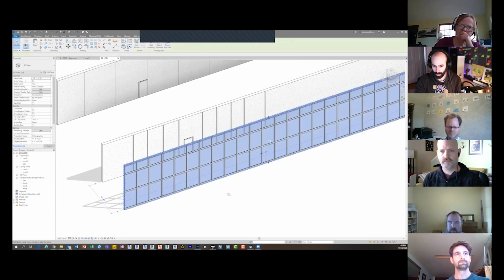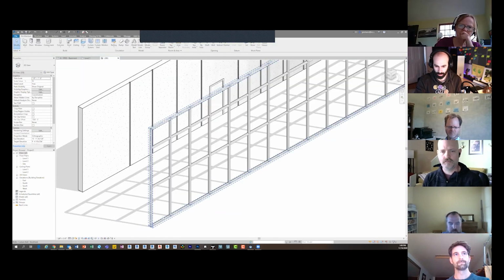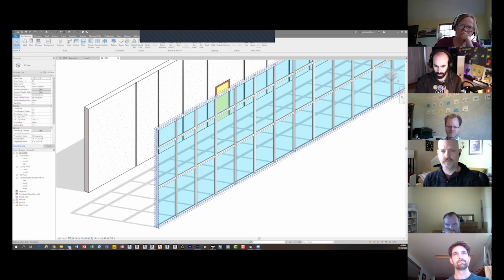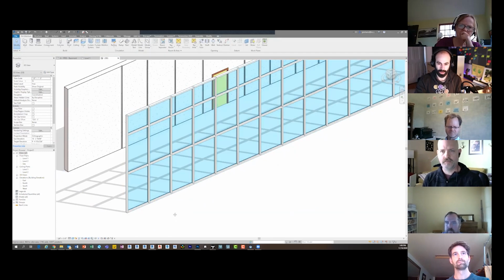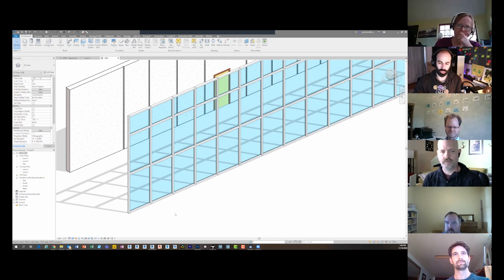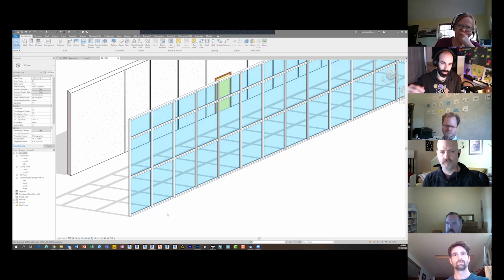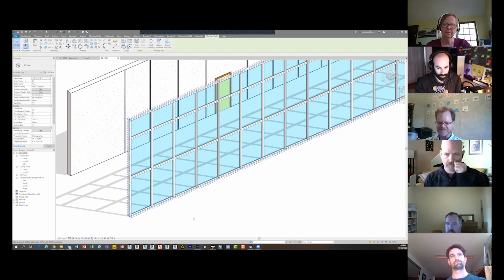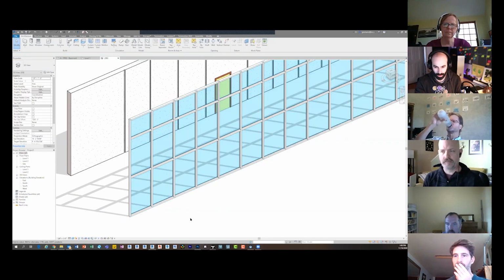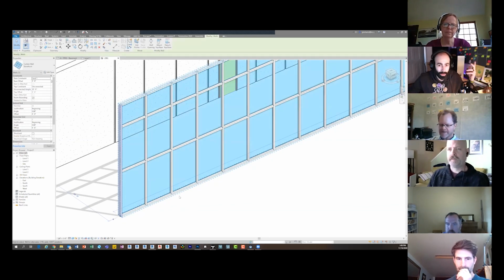Here's a storefront tool. And I've talked about this numerous times, but curtain walls, they're made for this, but the tool itself is extremely useful for so many other things, because what you're doing is you're able to host objects in a gridded system that you can control. So it's extremely powerful. And if you've seen any of my tutorials on like wood slats or metal panels and all that stuff, there's just so much you can do. Metal roof. Yeah, roofs. I mean, yeah, seam. Exactly. Standing seam metal roof. You can do studs if you want with it, right? I mean, it's just extremely, extremely powerful.